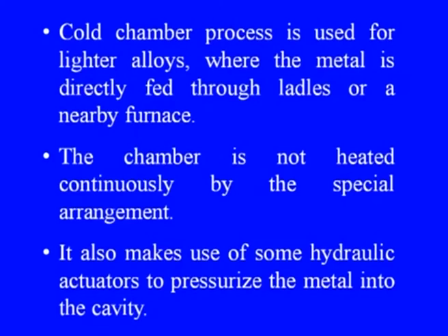The cold chamber process is used for lighter alloys, where the metal is directly fed through ladles from a nearby furnace. The chamber is not heated continuously by a special arrangement. It also makes use of hydraulic actuators to pressurize the metal into the cavity.